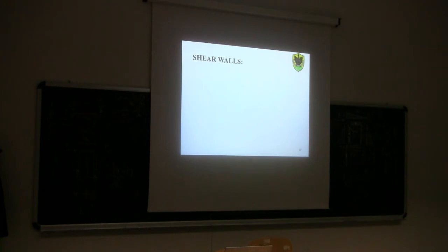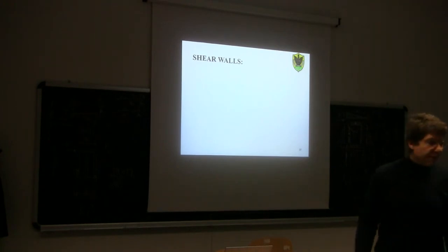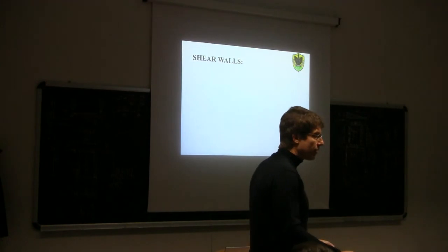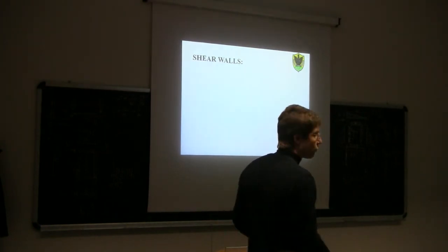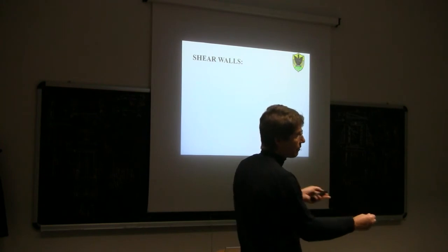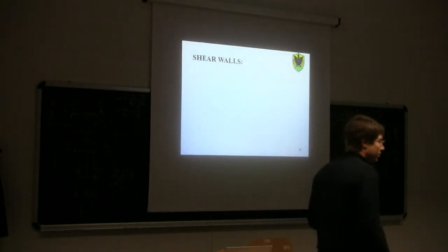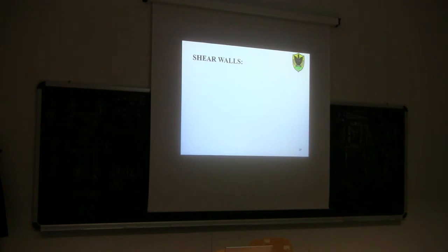Okay? So in the end, the final solution is obtained by superimposing the two cases of only gravity and lateral force. So, if you remember, the only modification will have to be made on the studs at the end. Because we said that due to gravity force, only the studs and the hold-downs in some way are loaded. So, ultimately, the state of design of timber walls.